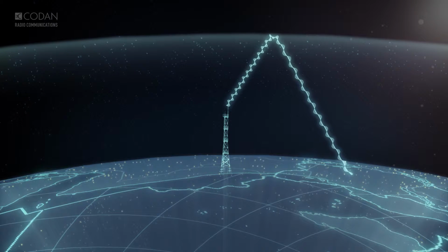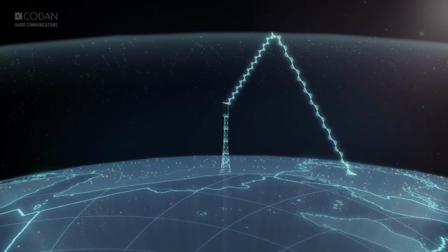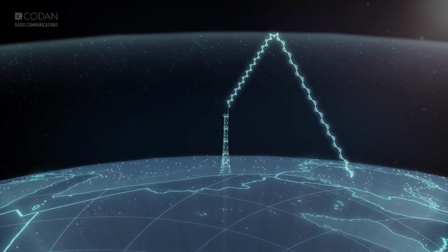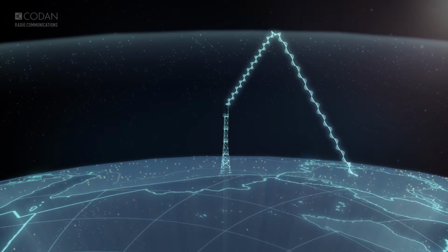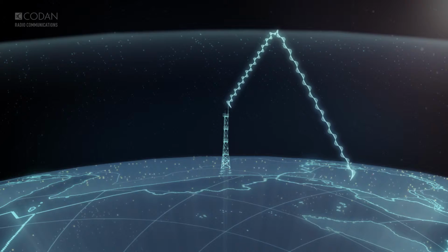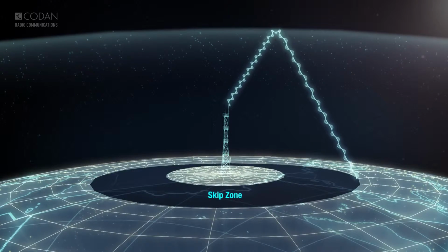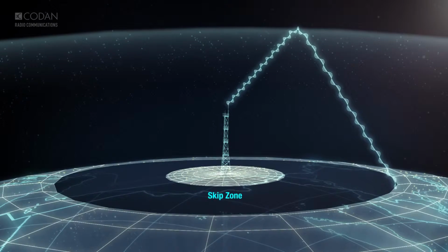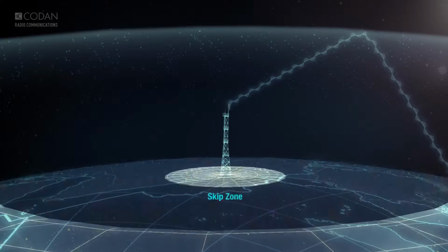A layer in the atmosphere called the ionosphere refracts the HF radio waves, making this technology work over long distances. The angle of the antenna is responsible for the coverage area, as it aims the radio waves which are bounced off the ionosphere. This also creates a skip zone, where the ground wave ends and the skywave starts, where the radio waves are not present as they are not refracted into this area.